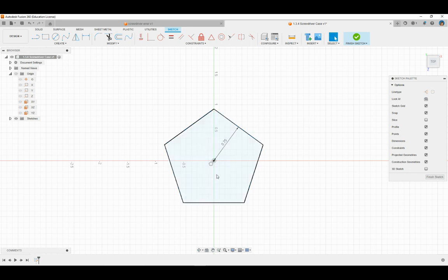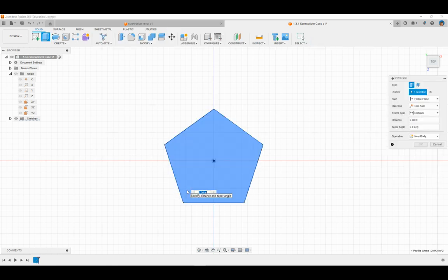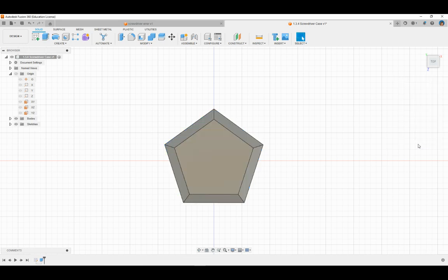We are now going to right click on the pentagon, and down in the marking menu, I'm going to select extrude. There's two extrudes here. There's a blue one and a kind of yellow-orange one. I'm going to select the blue one. I want to extrude this at 0.15 inches. But I also want to go over here to the extrude text box. I'm going to change the taper angle. We're actually going to angle this a little bit. I'm going to make this -45. And then you can click OK. And this is what it should look like at this point.